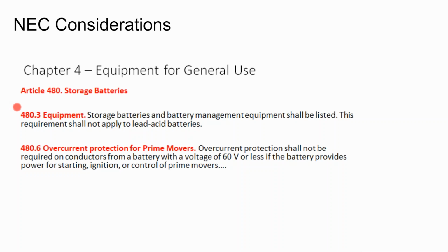So you might be able to find some used lithium-ion batteries online that are in the same price range as used lead acid. But if I put a refurbished lead acid battery into a home, I can still maintain code compliance. Part of that has to do with lead acid staying below 60 volts, whereas lithium-ion battery banks are high voltage, 380 volts.